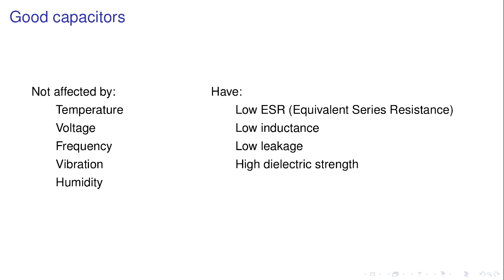Some capacitors have some degree of inductance associated with the wires and the way that the current gets distributed over the plates. They're no good for high frequency. But for a good capacitor, it won't be affected by that. If you jiggle the wires or otherwise vibrate the thing, it shouldn't be affected by that. And humidity shouldn't affect it in the short term. Over long term, I don't care, 20 years.